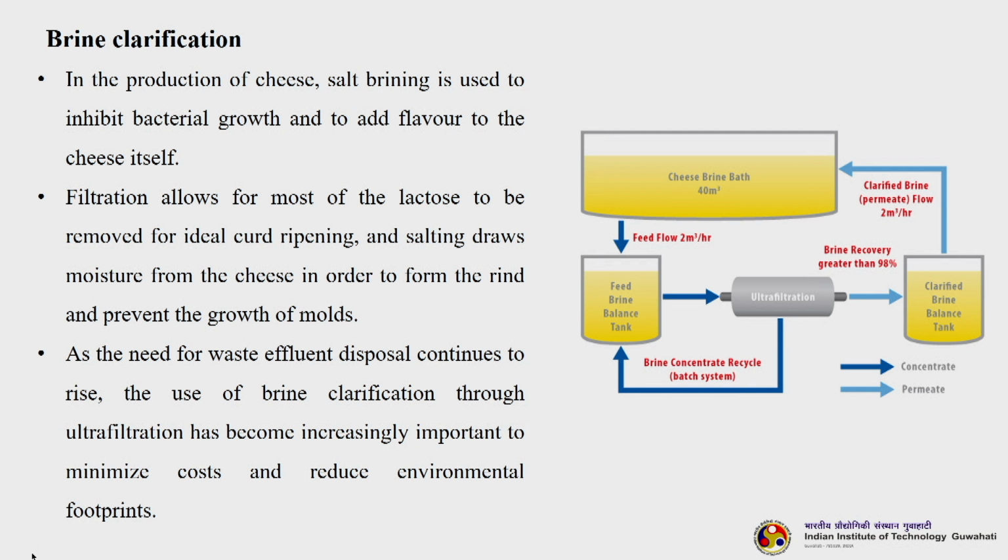As the need for waste effluent disposal continues to rise, the use of brine clarification through ultrafiltration has become increasingly important to minimize costs and reduce environmental footprints. You can see this is the schematic diagram of the brine clarification process. The feed brine passes through the ultrafiltration, and the concentrate brine is recycled to the feed tank. The permeate you can either collect, or you can send it to the cheese brine bath here for recycling purposes.